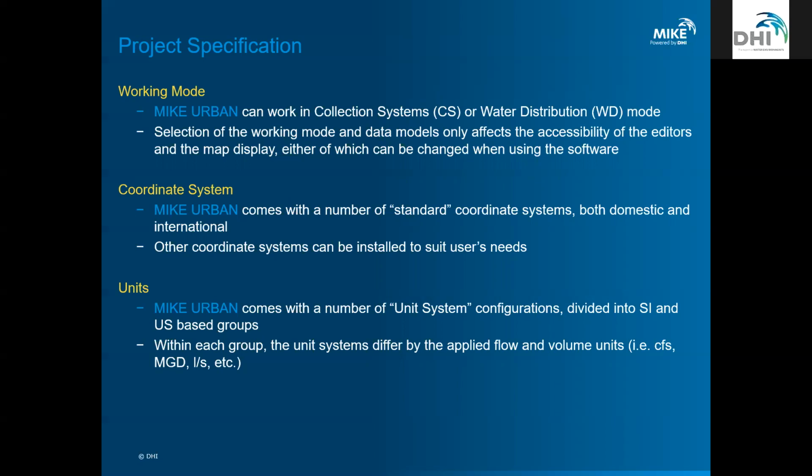Or you can just choose one of the standard, most commonly used ones. And then for the units, the same thing as well. You need to pick a unit-based system when you start a project. It can be changed later or specified for specific aspects. Here in the US, we commonly have clients that want the output in cubic feet per second for discharge, but also we have clients, if you're doing more pump operations or treatment locations, they might want MGD, or 1 million gallons a day. So you'll just need to pick one base system when you start.